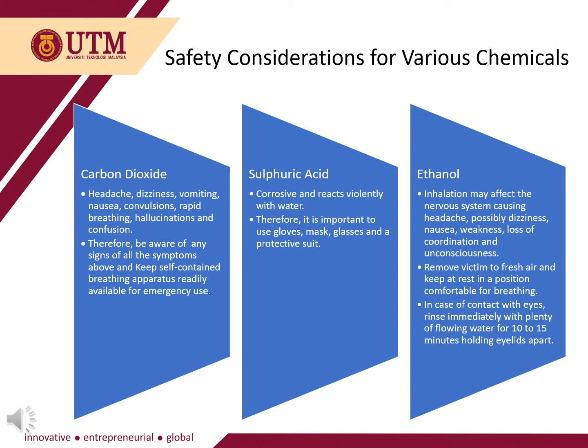For example, carbon dioxide will cause headache, dizziness, vomiting, and confusion. Therefore, be aware of any sign of the symptoms above if we are exposed, and keep all self-contained breathing apparatus readily available for emergency use. For sulfuric acid, it is corrosive and reacts violently with water. Therefore, it is important to use gloves, mask, glasses, and a protective suit.